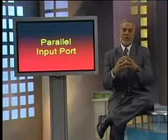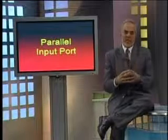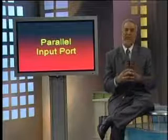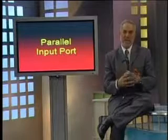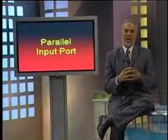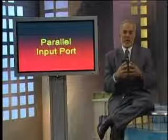The output of an 8-bit AND gate is now connected through another 2-input AND gate. The second input to this AND gate is the IO read signal, the control signal inverted.